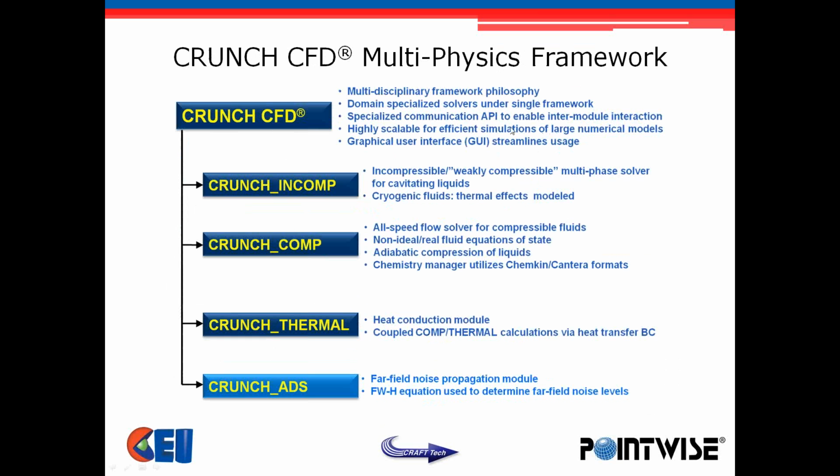Briefly, an overview of the Crunch CFD multi-physics framework. We have a multidisciplinary framework that involves a number of different solver modules. Currently, we have an incompressible solver for multi-phase and cavitating liquids, which also includes thermal effects modeling for cryogenic fluids. We have an all-speed preconditioned compressible flow solver that includes non-ideal real fluid equations of state, as well as a chemistry manager for chemically reacting flows.